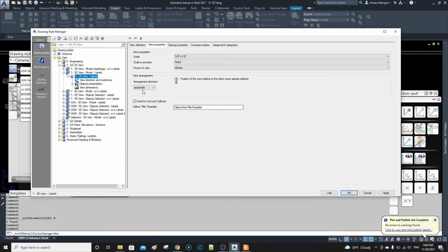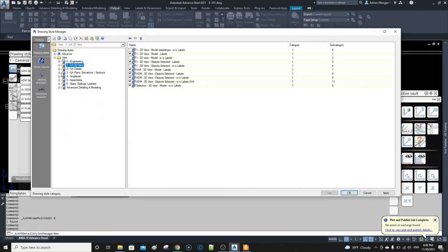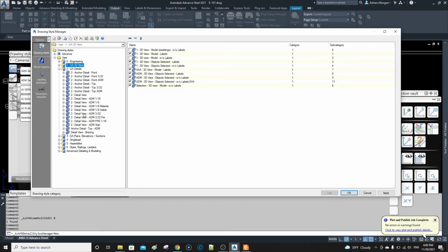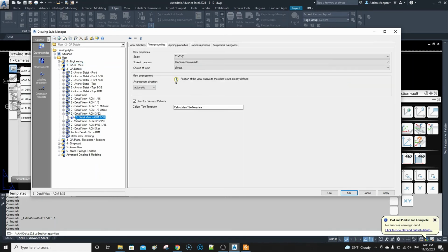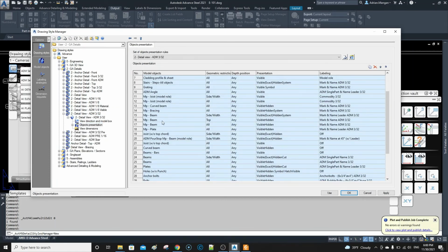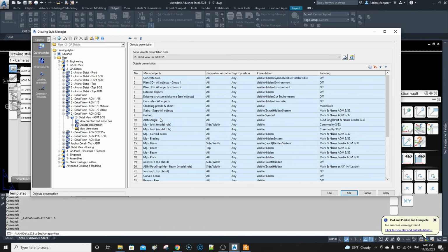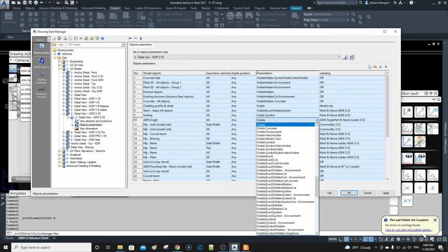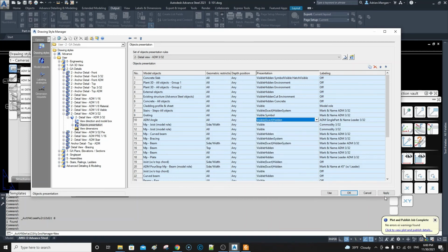And we want it to come in exact also, so let's go to detail view, object presentation, and it's not going to be main part beam, it's going to be this one here, visible, so it's not going to be that one. So it's going to be one with clips. Have I set up with angle? This one, visible all. So visible, exact, hidden, apply. Just check your size.